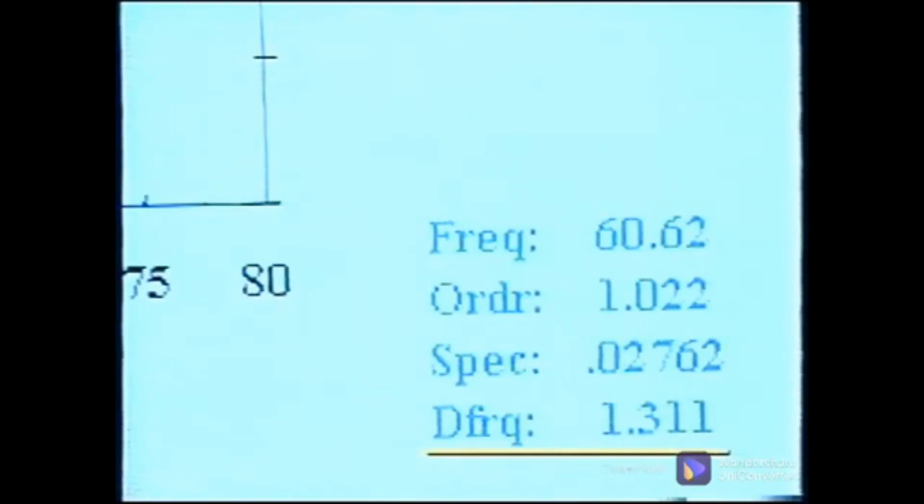They are separated by 1.3 Hertz, which is 2 times the slip frequency. It shows up at 2 times slip frequency because it is a two-pole motor.